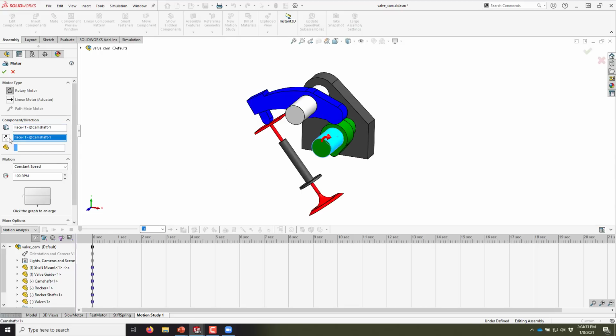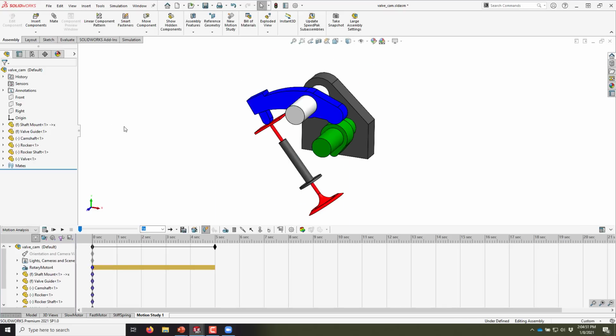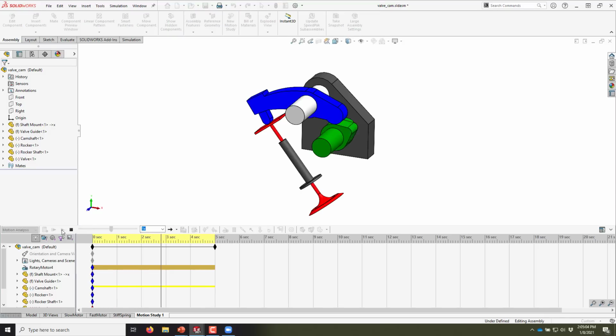Apply a motor onto this guy here. I'll spin it around. I want it to rotate this way because that's the way my cursor's been moving this whole time. This thing's going to be moving pretty quick because this valve is for an engine, so I'm going to do 1,000 RPM. Okay, and let's test that out. Let's see what 1,000 RPM looks like at our 5-second time scale. If I hit calculate, that looks a little funny. It's just kind of flickering at me. So what's wrong there?